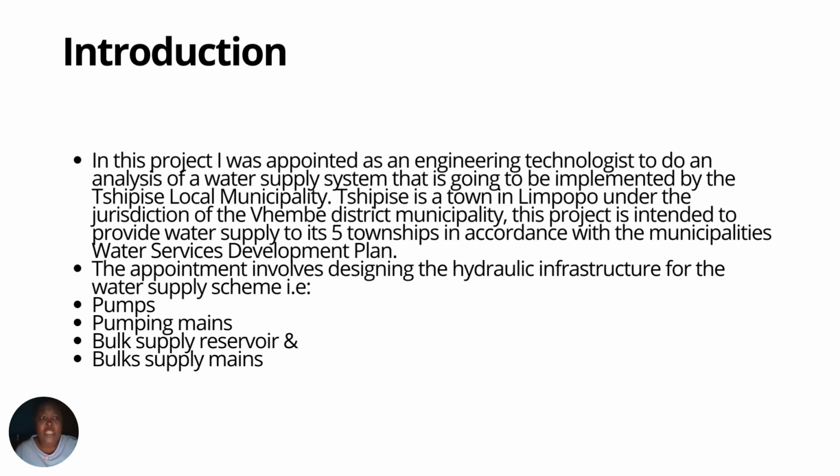This project is intended to provide water supply to its 5 townships in accordance with the municipality's Water Services Development Plan. The appointment involves designing the hydraulic infrastructure for the water supply scheme, for example, your pumps, pumping mains, bulk supply reservoir, and bulk supply mains.